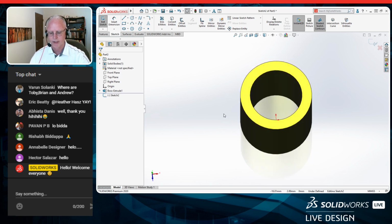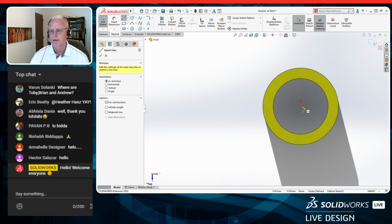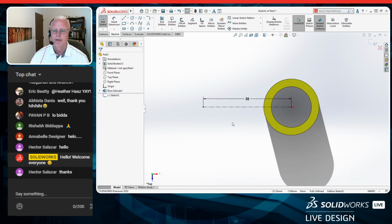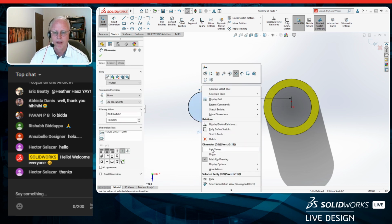So let's jump to a top view here, and I'm going to draw in the center line. I like to use center lines because they're visual for me. They help me understand that relationship. I'm going to type in 35 because our bolt circle was 70. Half of that is 35. I'll draw a circle in here. This one is going to be 12 because the radius for that was 6.